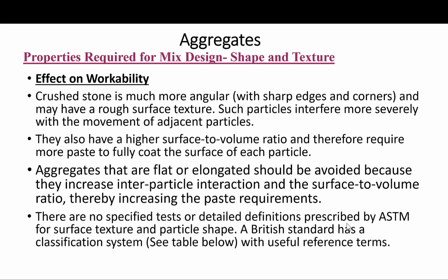Basically, there are no specified tests or detailed definitions prescribed by ASTM for surface texture and particle shape. Although ASTM C1225 does promote an indirect measure of both by measuring their effect on the void content of fine aggregate, there is no such specified test for this property.